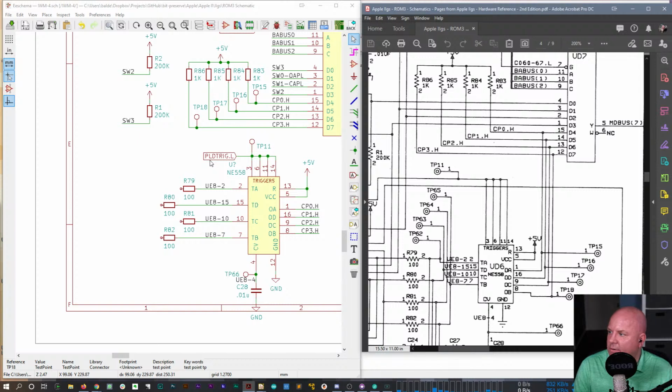What is the difference between normal ground and chassis ground? Chassis ground is usually connected to earth mains. Yeah, as said in chat, chassis is literally the chassis. Usually, like in the digital part of a circuit, you want everything connected to the same ground reference, and then that ground reference should be connected to whatever other ground references you have. And you can usually do that through stitching capacitors.